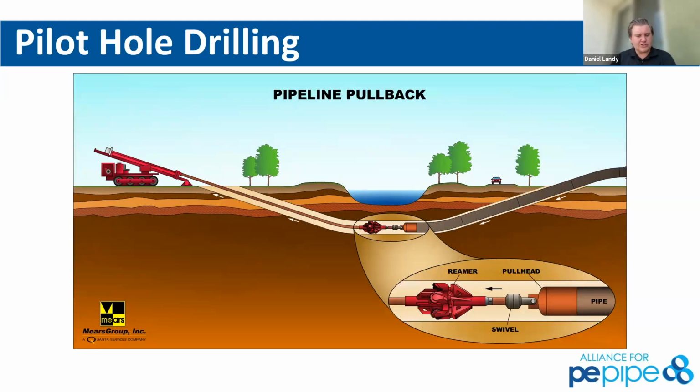And the one last interesting thing I wanted to mention about HDD, it's the only method where you're actually launching the equipment at grade or at surface. I mean, you can lower it by putting it in the trench, but it's not necessary. You can drive that machine right up to the side of the road, drill right under the road if necessary.